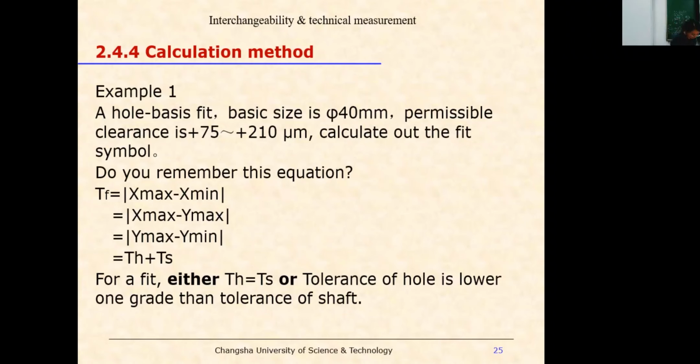So you take the table. Shaft is 32, right? So the diameter is 40. Choose the 40, this line is 40, so it is smaller. Minus 79, 75. So you can choose minus 80. Minus 80, yeah, it meets the requirement, right? So the 80 is D. This is D for the shaft, right?